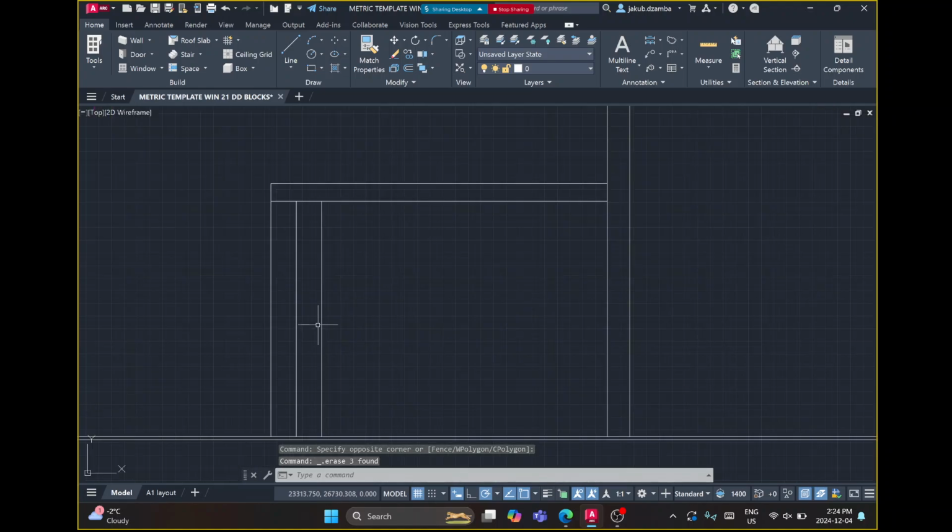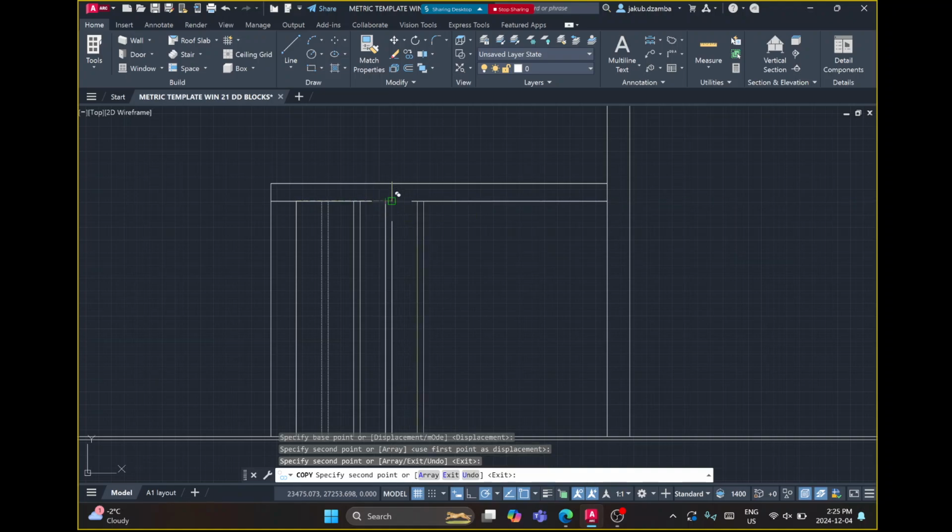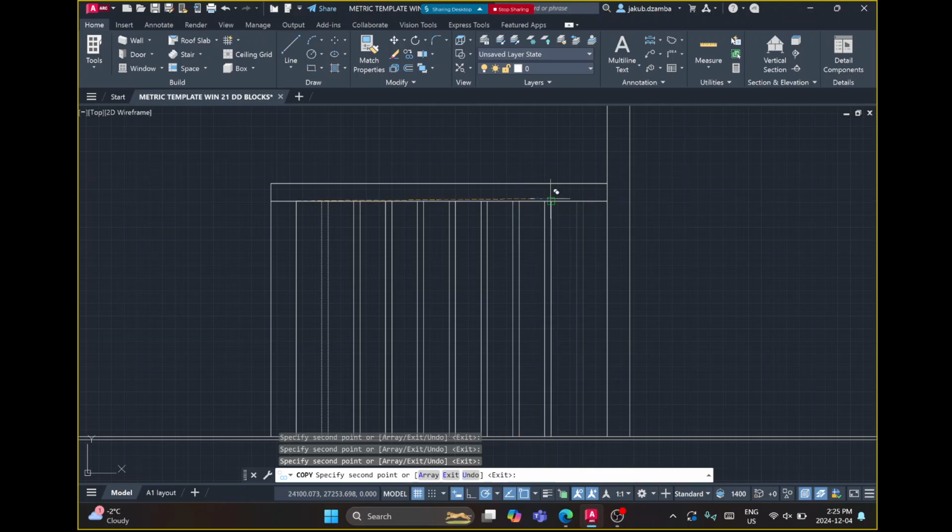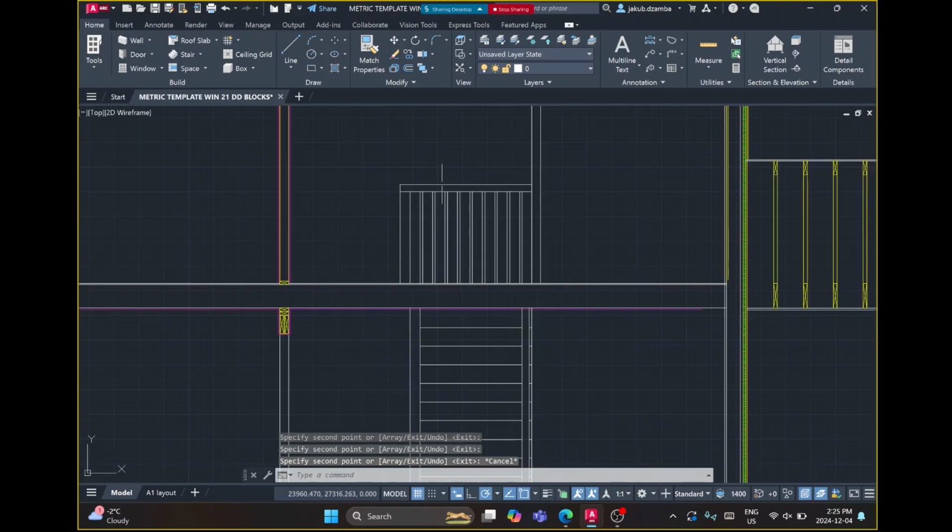Okay, now the pickets, you can see pickets between the panels of the railing outside there in the hallway, but in this case we can say, I don't know, they're 25 millimeters. So I'm going to say offset 25, like so, and then I can just copy them doing that leapfrog technique we've done several times. Done.